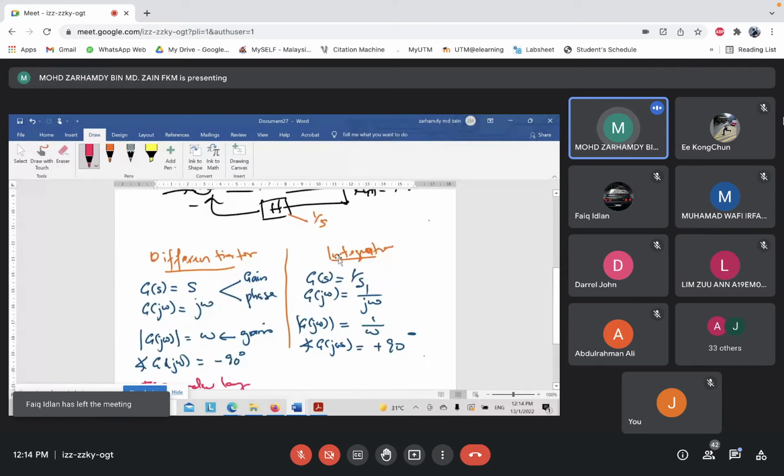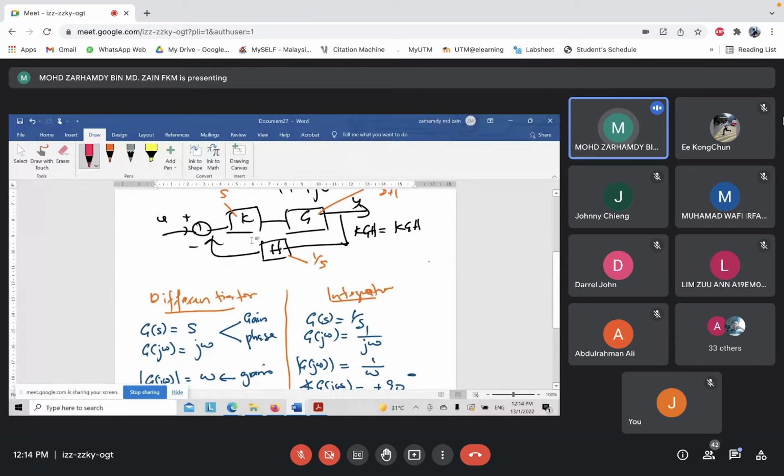Okay, so because in our system, maybe it comes from our subsystem. If you refer to the previous chapter, once you design the model, for example, if our model has 3 elements, spring, damper, and mass, so it should have 3 blocks, right? Each block represents the stiffness of spring, mass, and also C. So that means every block has their own mathematic equation.